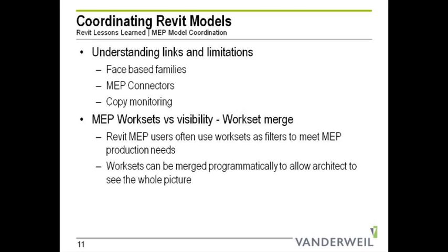Now, in 2011, Revit introduced copy monitoring for MEP systems. You might be familiar with copy monitoring, but basically what happens is I can choose to copy all the light fixtures in an architectural model, and then the monitoring part is that if you move it in your model, when I get an update, it's going to move it in my model.